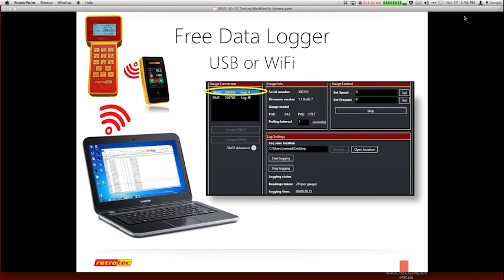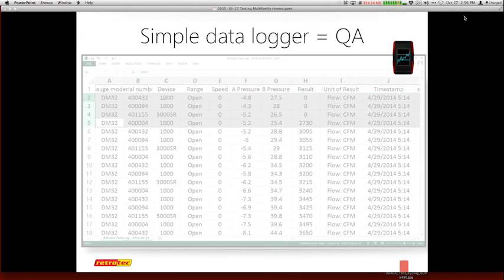But sometimes there are little glitches that happen in Wi-Fi that we aren't aware of when we are watching stuff on a screen or surfing. But your data will have little gaps when you have Wi-Fi. So I highly encourage you to think about using a solid connection. Depends on what you're after. When I'm using a virtual gauge, it's not really identifiable that I may have had little gaps. So I would definitely encourage you to do more of a wired system.